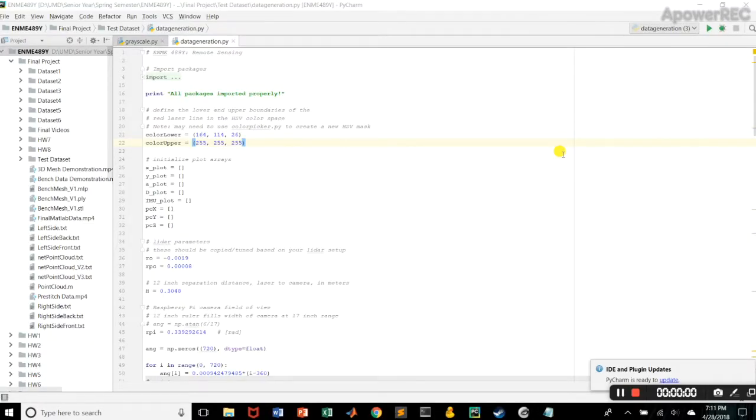As we touched upon earlier, we want to use a combination of Python and OpenCV to extract distance measurements from the JPEG images that are captured with the Raspberry Pi camera. In the beginning, we first define the upper and lower bounds of the red line laser color, because in the JPEG images we want to be looking for that color so that we can get distance measurements from it using the calibration code and the geometrical lidar strategy as described earlier.